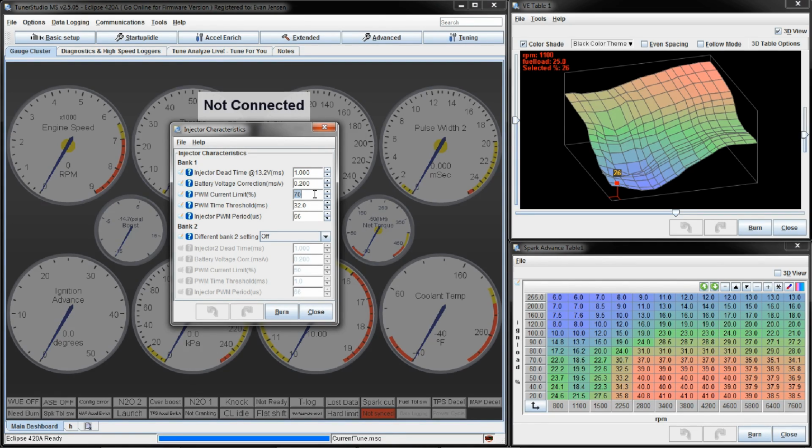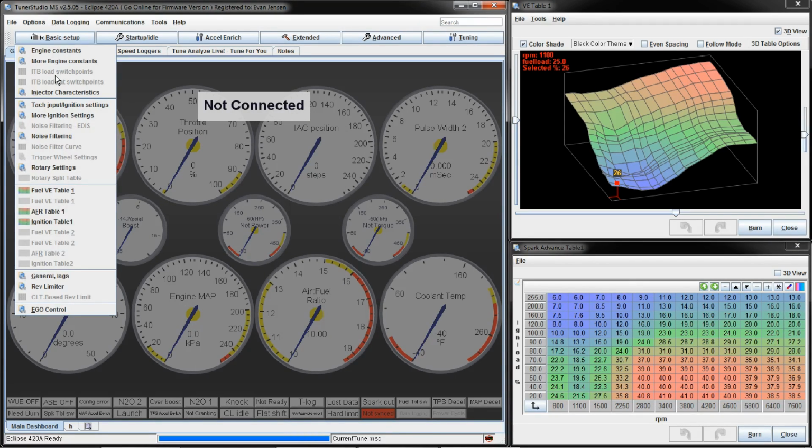I may talk about that later, although I think I've already mentioned it in past videos. Check out the fuel injector video if you haven't; I spent a lot of time talking about fuel injectors on that one. Anyway, this setting here is for low impedance injectors. I'm using peak and hold on this Megasquirt 2. You won't have this stuff if you have high impedance injectors, which are a lot more common, or people use a resistor box. But I didn't want to source or install a resistor box, so I'm doing this in software, which I really like the ability to do.